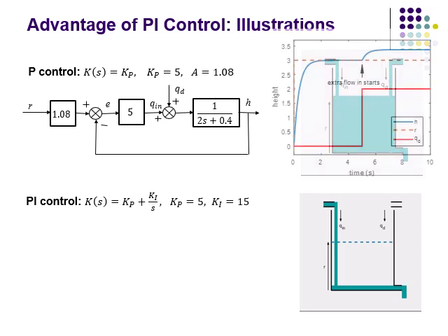Okay, so that just shows the animation again, and then if we plot the graph, here we've got 3 signals. The dashed line is the reference, the blue line is the height, and the red line is the additional flow, Qd. So you can see that initially when the extra flow Qd is 0, the height increases to match the reference of 3, but then when the extra flow into the tank starts, we get an increase in the height, and so in steady state the height of fluid is too high.